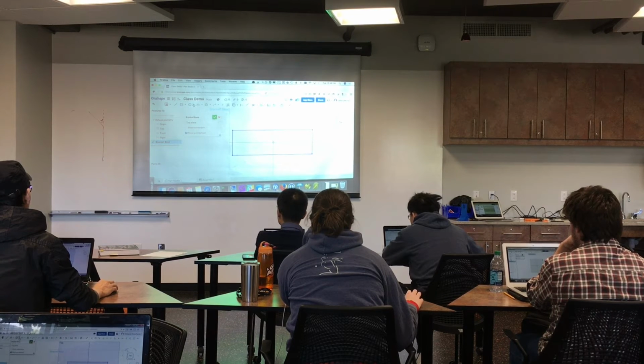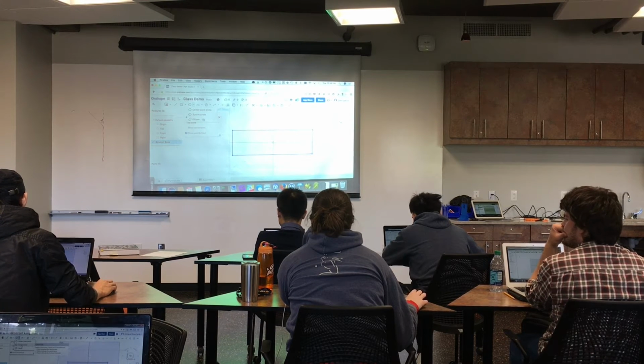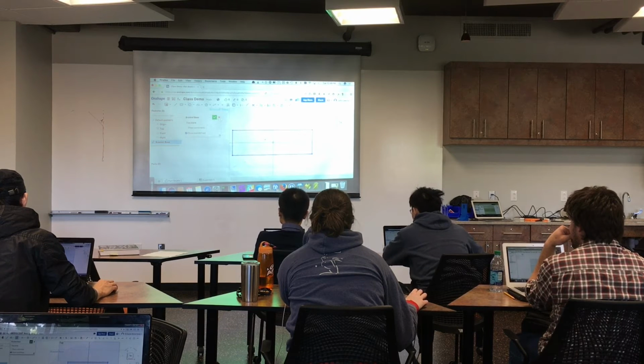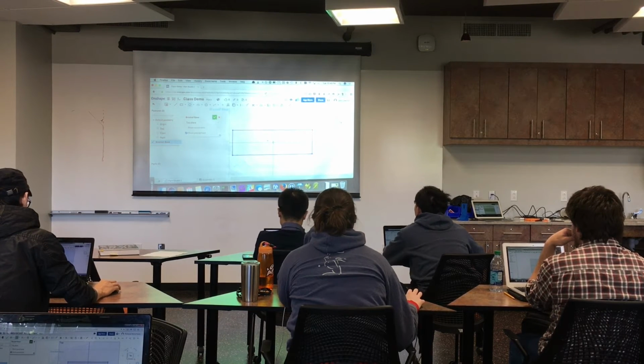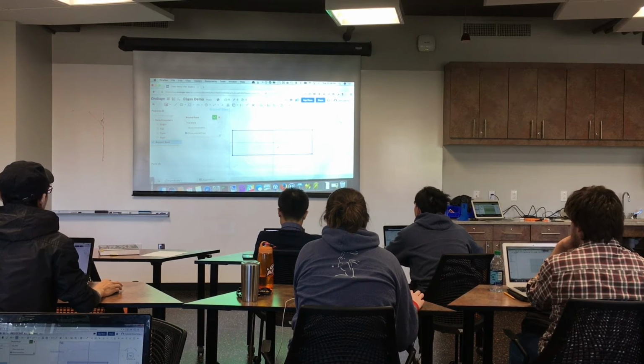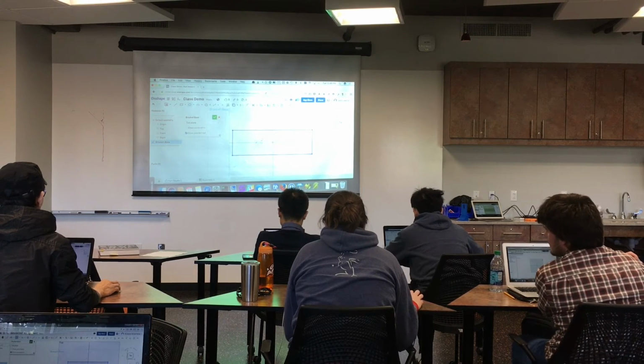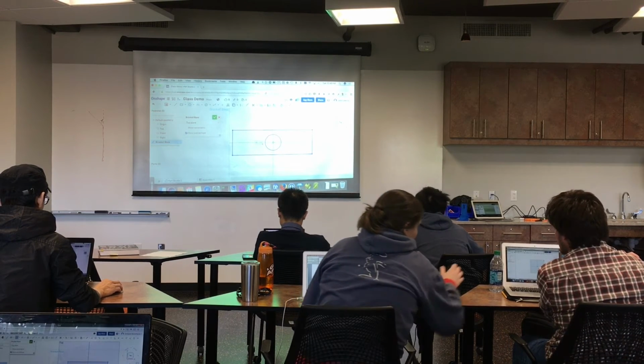For circles, if you click the drop-down arrow, you see you can do a center point circle, a 3-point, or an ellipse. We want center point circle. And we've got 3 of these on this sketch plane. So go ahead and hover over the origin until it highlights again and drag one out. That's going to be the hole for our DCDT.